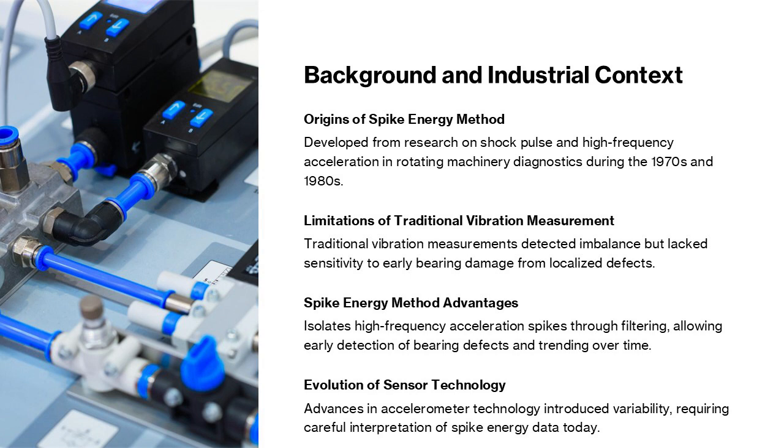As a result, maintenance teams could trend a single parameter, spike energy, over time and identify abnormal increases associated with defect initiation and progression. This approach was particularly attractive because it reduced complex vibration signals into a manageable diagnostic indicator.